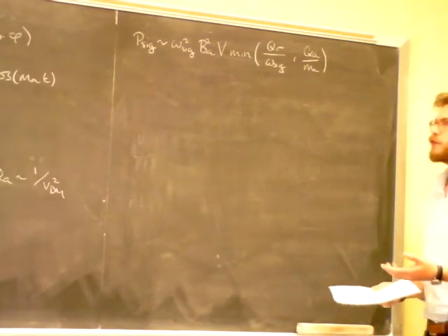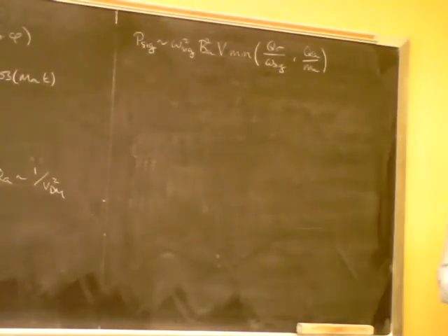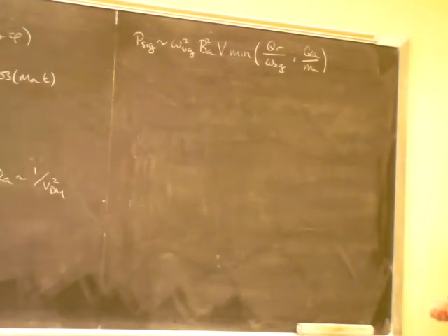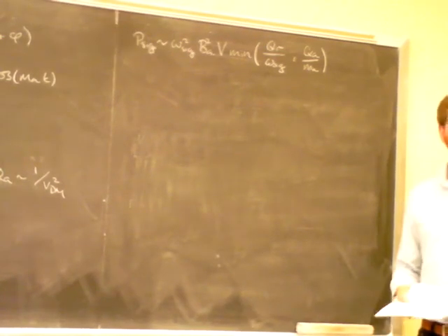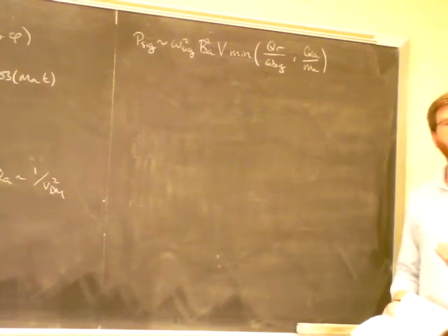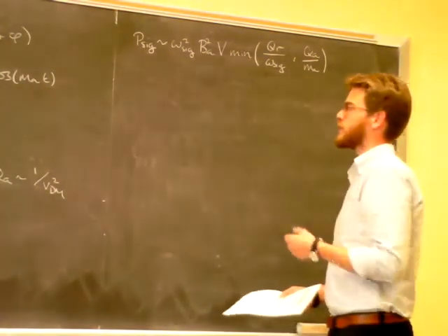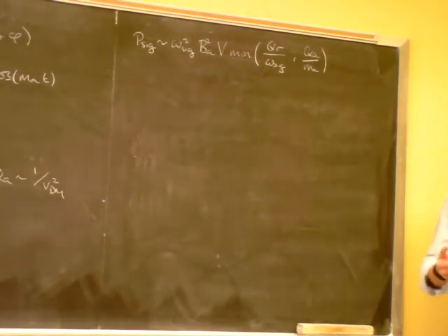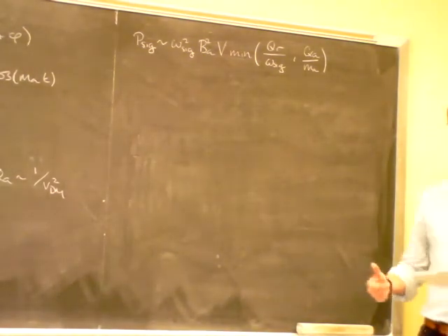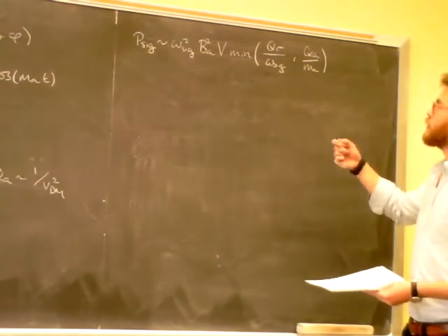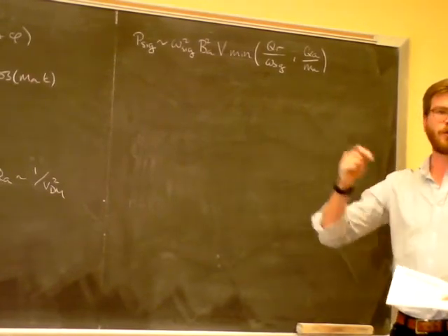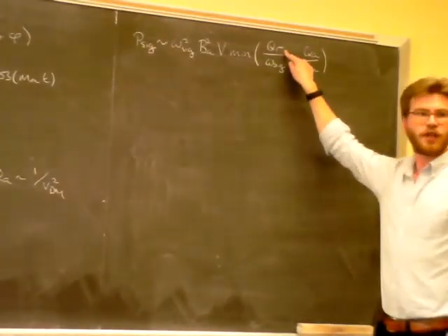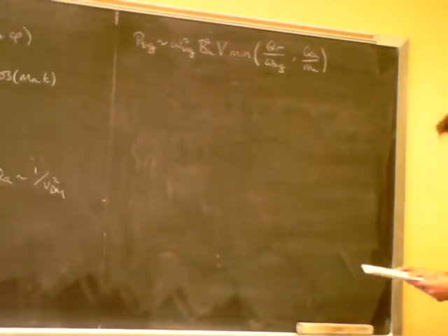Now, for those of you who may have forgotten, an LC resonator or RF cavity, which can be explained as an LC resonator, is basically a damped harmonic oscillator. If you remember your damped harmonic oscillator equation, it has a second order derivative in time, and a first order derivative in time piece, which is the damping term, and that has the definition of what the Q factor is. So you can think of it as, if you do your experiment for a long amount of time, eventually your signal will saturate once you've gone through Q cycles of oscillation at frequency omega signal.